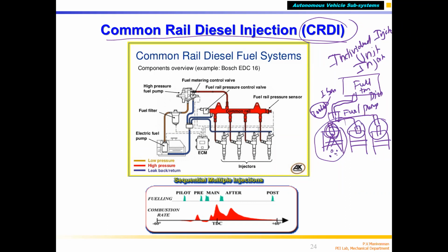When the pressure is less, the injected fuel will not become atomized into smaller droplets. The fuel itself will go inside as bigger droplets. The droplets will become bigger if the pressure drops inside the injector. Because of that, not all the fuel will burn. Even though each individual droplet starts burning, if the droplet size is bigger, all the diesel fuel will not evaporate, correct?